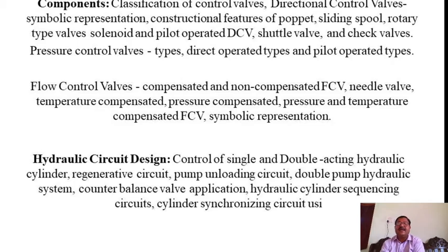Here the single acting hydraulic circuit does only one simple work. If there is simple work, and you don't want to add further work, at that time the single acting hydraulic cylinder is used. The only thing is it will unload or load. After loading anything, the oil has to come down to the reservoir. After unloading anything, the oil that is in that single acting circuit should come down to the reservoir, or the oil tank.